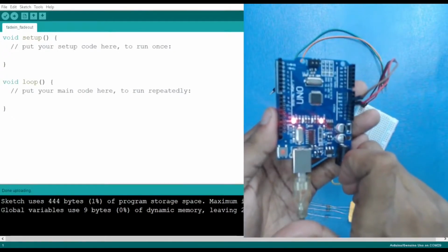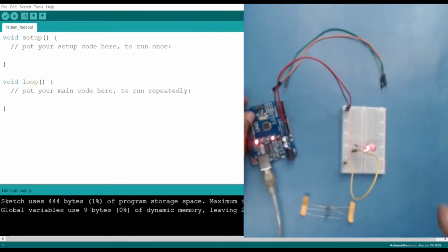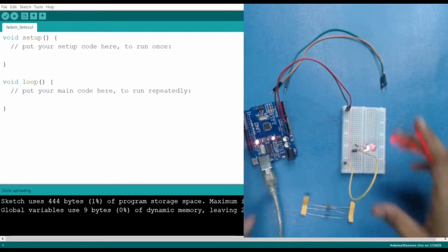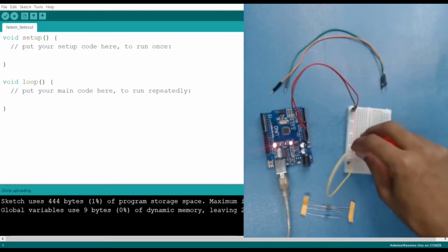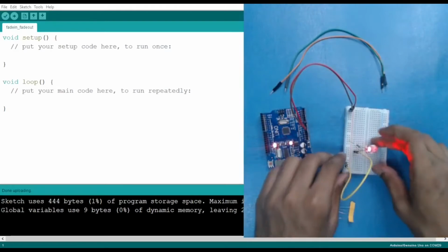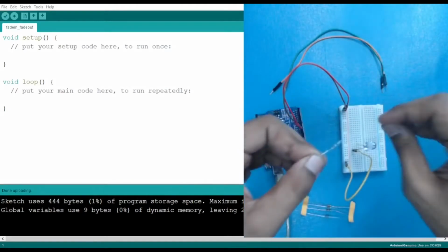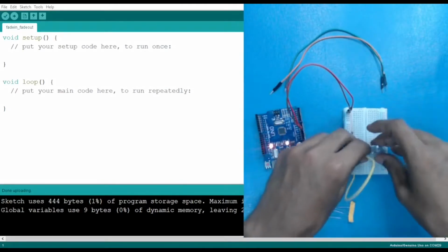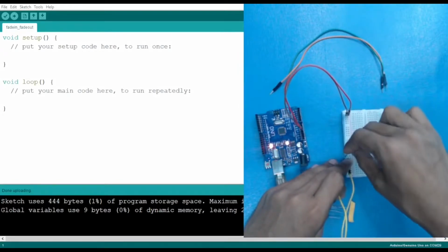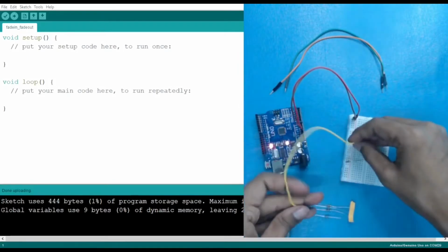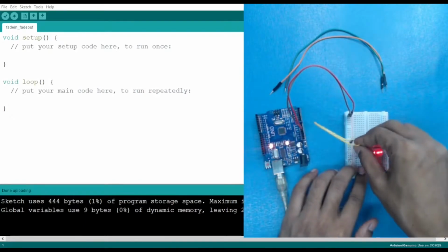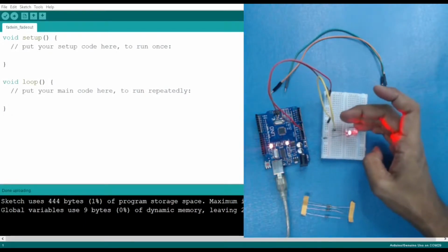We are going to use those pins here, because on those pins we can change the duty cycle, that is the percentage. Instead of normally taking just high and low, we can give a value like 50% high, or 30% high and 20% low, like that. So this is my simple circuit. Now let me change something in my connection. I connect the negative with the resistance and the positive directly. So nothing has changed, I just changed the resistance position.